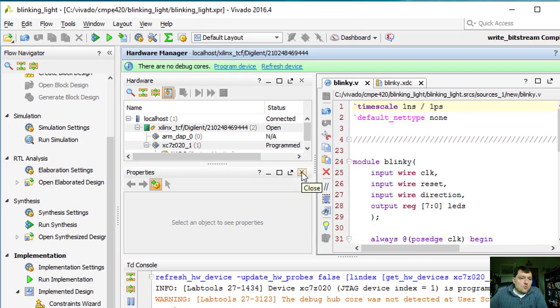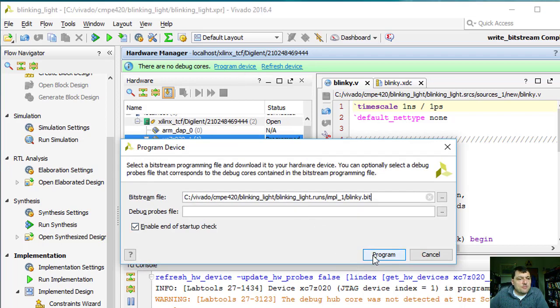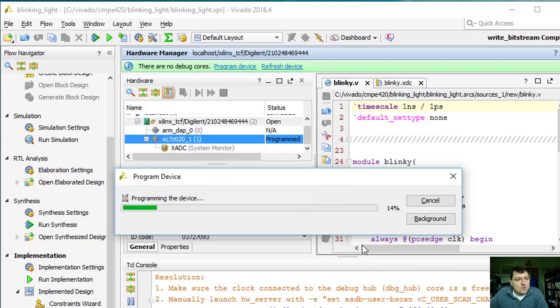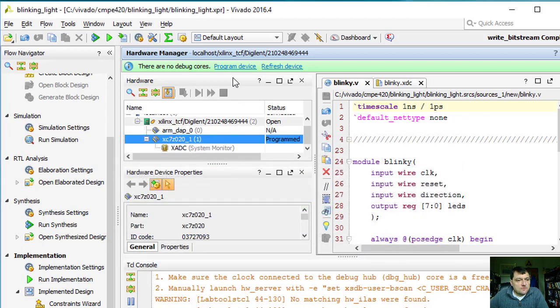And one of the things about Xilinx that drives me crazy is these little pop-up boxes that are easy to miss. I was looking around for 5 minutes trying to find why I wasn't programming my device. I wasn't hitting that one little pop-up button. What you're doing is really picking which of the different programmable parts it found. So on a complicated board you may have multiple targets that you can connect to and program. And in this case, I just want to program the Zynq.